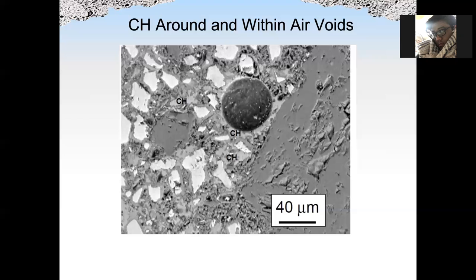Okay. In future lectures, we will also discuss SEM, the scanning electron microscope, and how and why this machine works. The machine sends electrons into the samples, and depending on the reflection, because in the air bubble there's nothing, and nothing can reflect the electrons, that's why we see black. Okay, if reflection is higher, in the case of unhydrated cement, we see a much brighter phase.